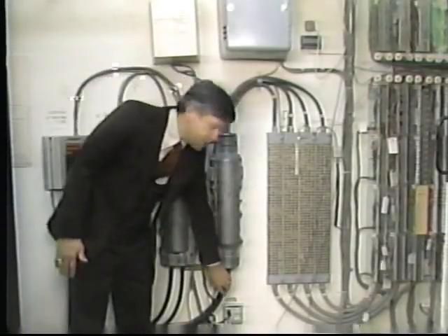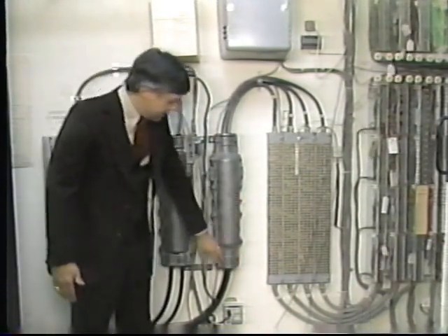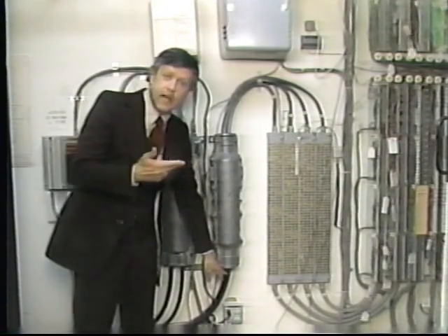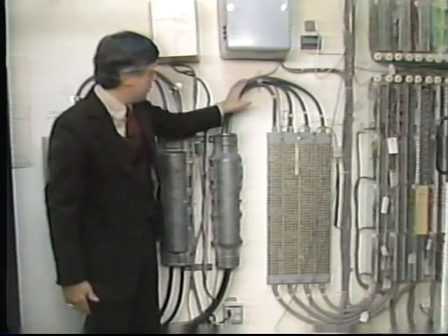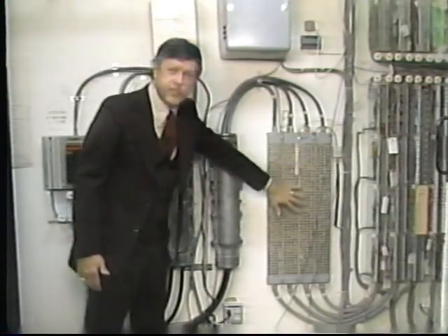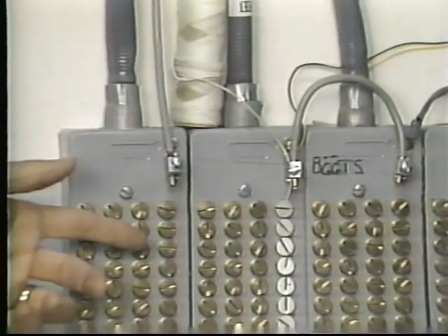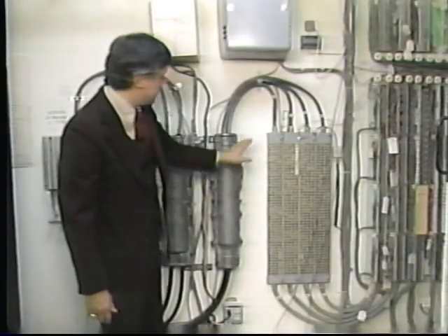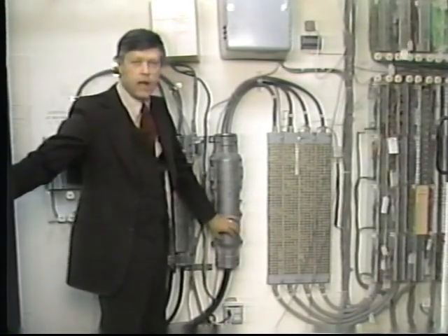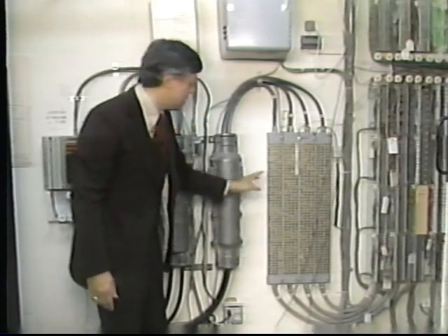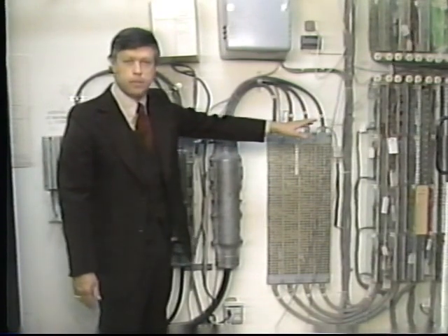Now here, our telephone cable, which comes from the phone company, is brought into a splicing case. Since the cable is really dead-ended and cut off, the wires have to be spliced and brought through here to what we call the station protectors. These are, in effect, each one of these screws has underneath it a fuse. And what happens is any electrical discharge outside the system, such as lightning or other high voltage that may cross into these lines, will cause the fuse to blow here and protect the telephone system in the building.